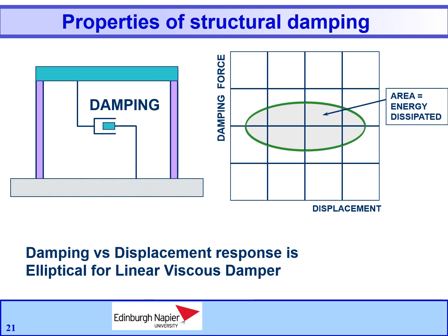As mentioned earlier, the damping in actual structures is usually represented in a highly idealized manner. We have been using a linear viscous damper under the concept of an equivalent viscous damping approach that encompasses the energy dissipation in all damping mechanisms.